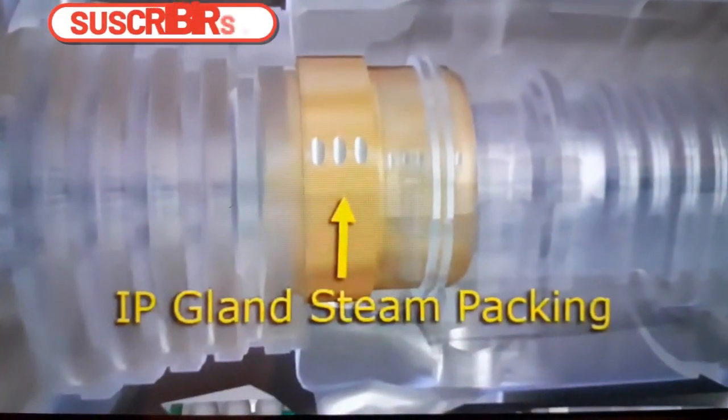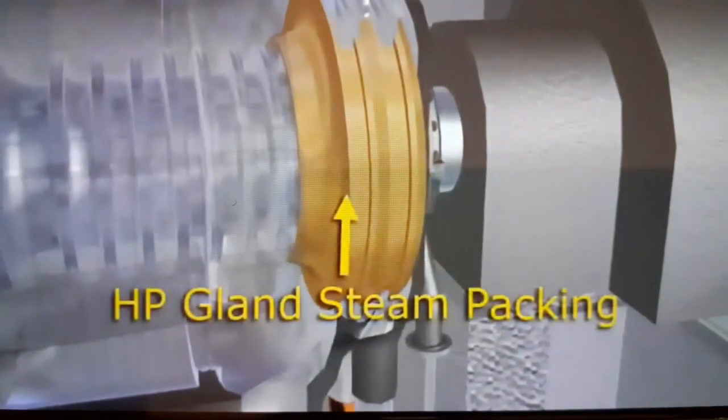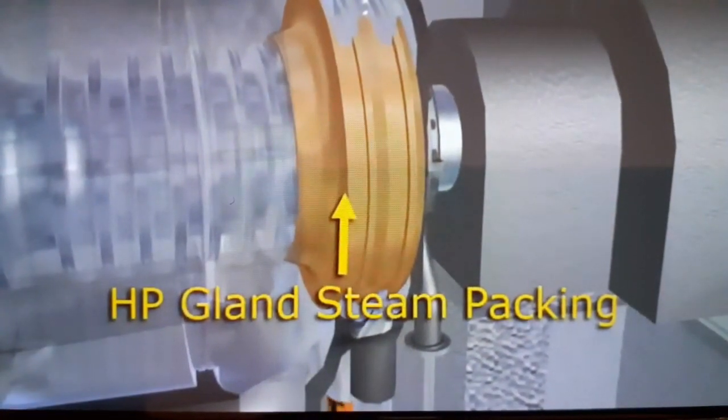The intermediate stage packing is located at the reheat steam inlet and is a seal between the high pressure and intermediate pressure sections of the turbine. The high pressure packing is located on the generator end of the turbine rotor.